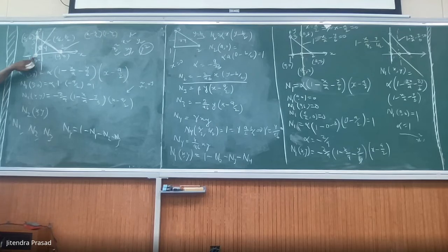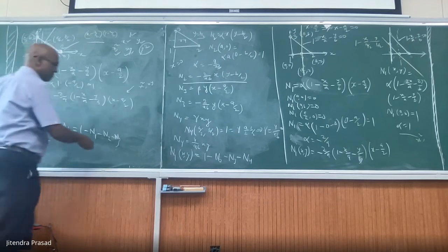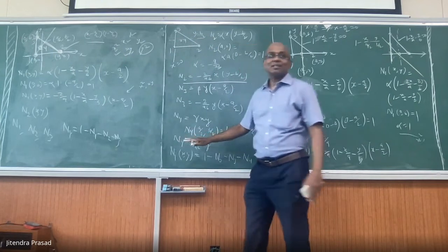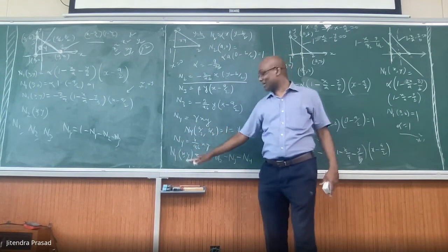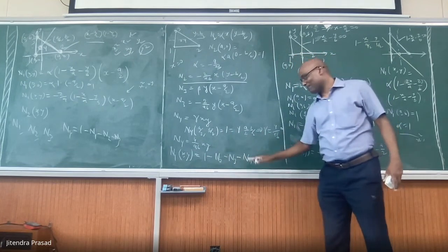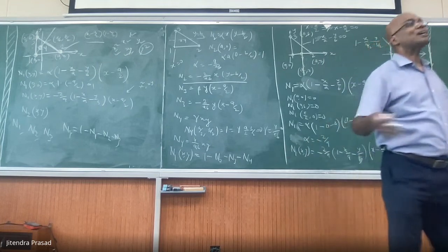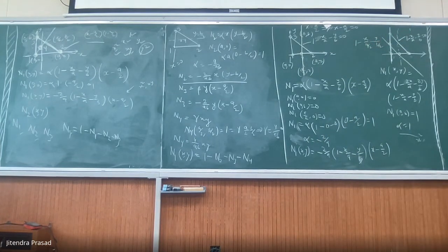It doesn't fit here. You are right. Finally, the equation will be something like that only. But it doesn't fit the story that I was telling, that you look for two equations passing through the other nodes and you multiply them. It's not obvious whether it should be like that. You are right that actually it should be like that only. In fact, when we look at the four nodal element, that's what we will write. We will write the same thing. So in that case, we do the ones which are easy, and then the last one remaining, we say N1 equal to 1 minus N2 minus N3 minus N4. Automatically, it will have x, y, and constant terms, because all others are in those terms only. And you get that.